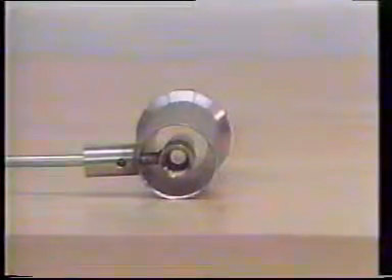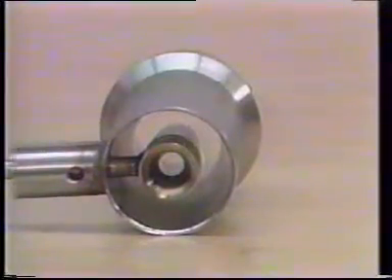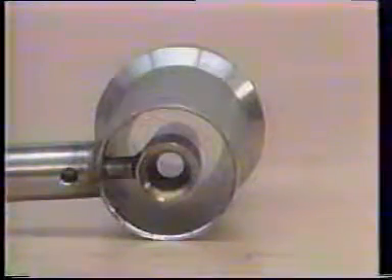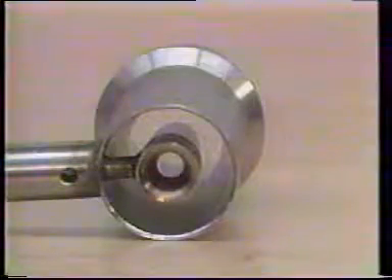Other widely used types of head-producing differential pressure flow meters include flow nozzles and venturis, as we see here. Their basic principles of operation are similar to the orifice plate. A venturi consists of a converging conical inlet, a cylindrical throat, and a diverging recovery cone. Unlike orifice plates, venturis are well suited to flows with solid content because the walls and throat are smooth and will not trap and hold the solids. Otherwise, their performance and limitations are comparable to orifice plates.